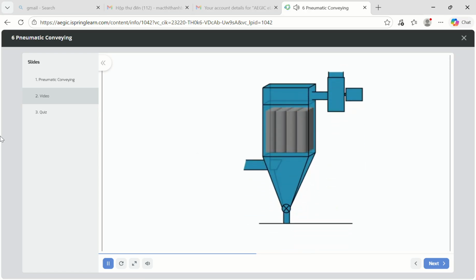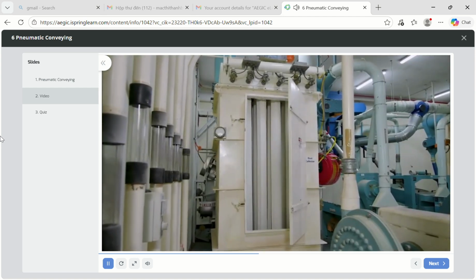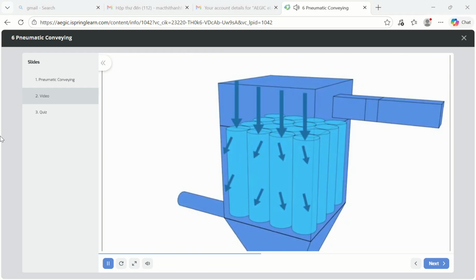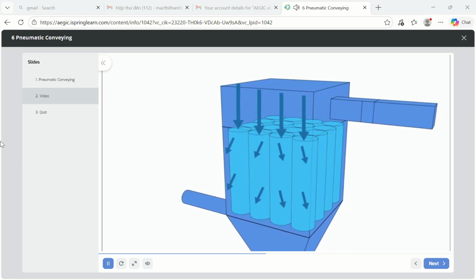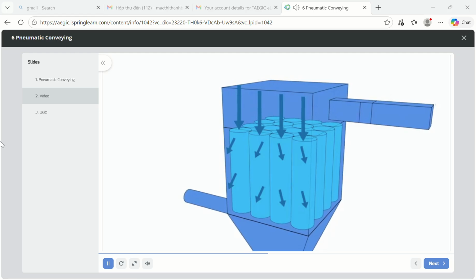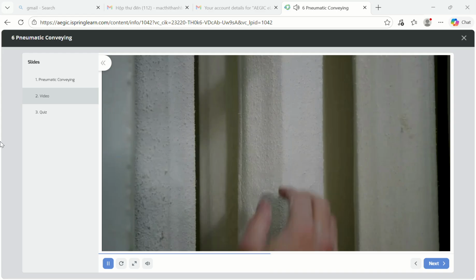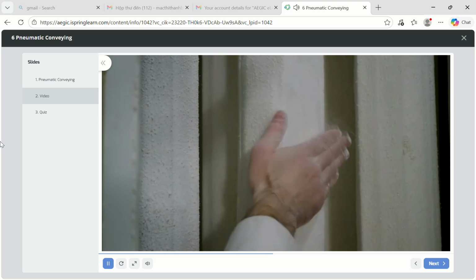Other types of filters rely much more on fabric filter sleeves to separate the solids. The filters are usually cleaned by a system that intermittently blasts compressed air into each filter. The blast may only last a fraction of a second. Only one row of filters is cleaned at a time. Despite the automatic cleaning, the filter still needs to be cleaned or replaced periodically to allow air to keep flowing.